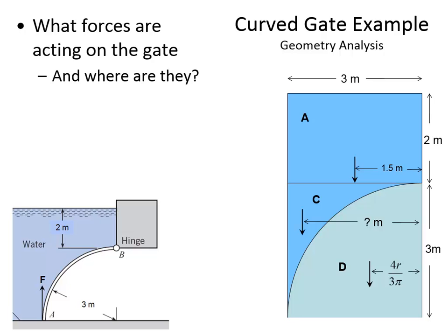So the opening force is 412 kilonewtons when you add all these together and then divide by 3, which is the moment distance that F has from the hinge. So that's the force required to just barely begin to open it up. We'd have to have a force just slightly greater than that in order to begin rotating it.